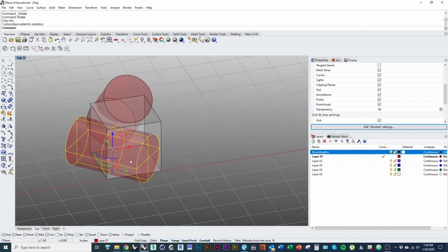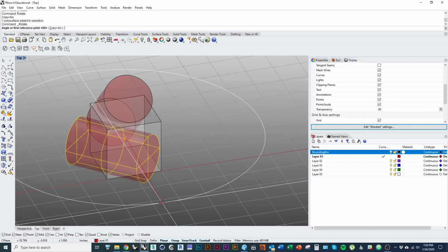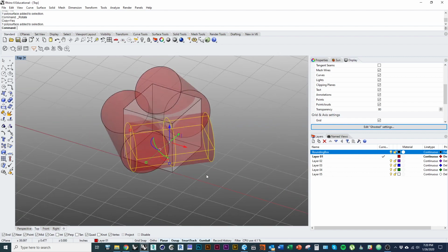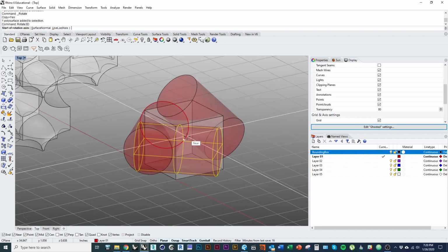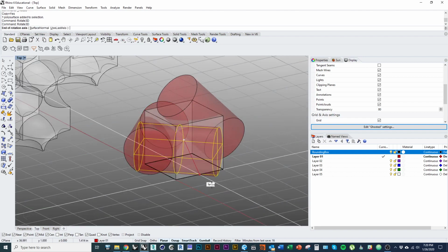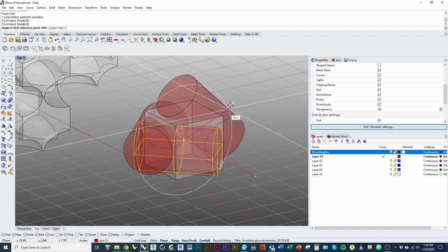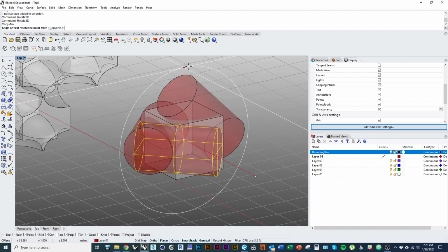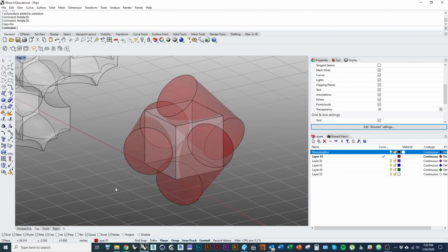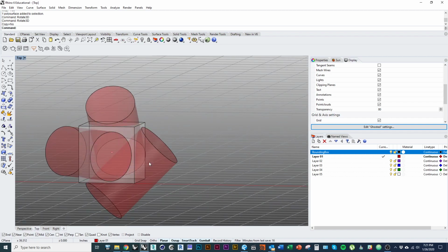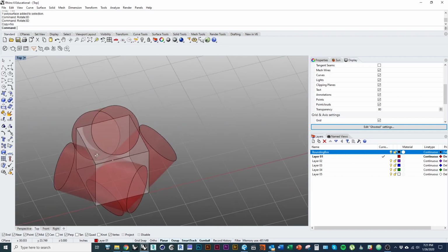If we select this geometry, again, I'll rotate it. This time I am going to turn on copy. Rotate it 90 degrees. Select it. This time type rotate 3D. Snap to the center point. Oops, messed that up. Snap to the center point. Draw straight out. Option copy turned off. And then rotate it 90 degrees. And there we go. So now we should have a box with a cylinder moving through 3 sets of 2 adjacent faces.